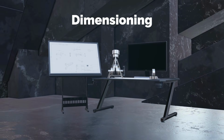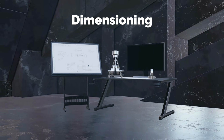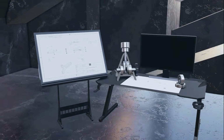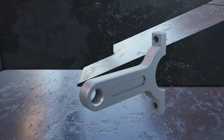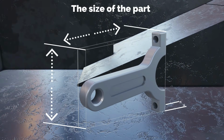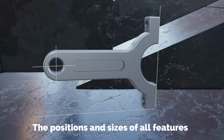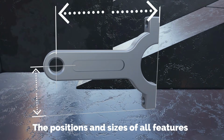Let's think for a moment about the main aim behind the use of technical drawings. We use technical drawings to describe parts. This description could be used for manufacturing or for quality control. It could also be used for cost calculation. In any case, to properly describe a part, not only will you need to define the size of the part, but you will also need to define the positions and sizes of all the different features of the part as well. And this is basically what we call dimensioning a part.